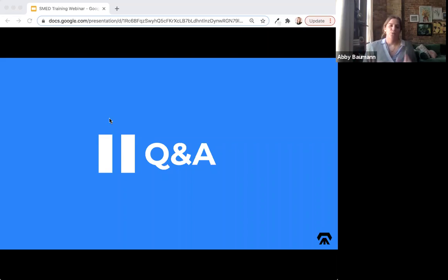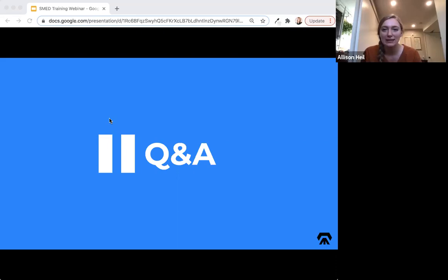Can you just briefly go over the difference again between extracting and converting? Yes. So extracting is when you don't really have to do a lot of work to take a step from being an internal step and take it out and do it before or after the changeover. Converting means that you're going to have to do some work. We'll get into some more examples specifically of what converting actually looks like. But usually you can break out the step into different parts and do certain parts before or after.